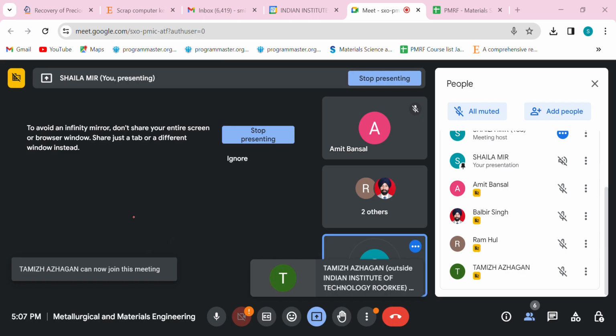Then we have another question that says Coble creep. Creep is a phenomenon where we have some constant loading at high temperatures. So there are different types of mechanisms or different types of equations associated with creep. One of that is Coble creep, right? So you have to say it is associated to which type of creep. It is dislocation creep, grain boundary sliding, lattice diffusion creep, grain boundary diffusion creep.